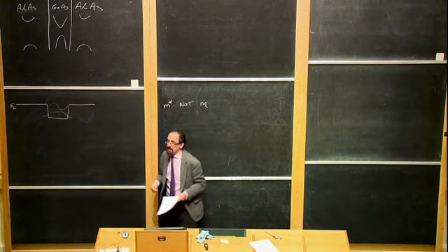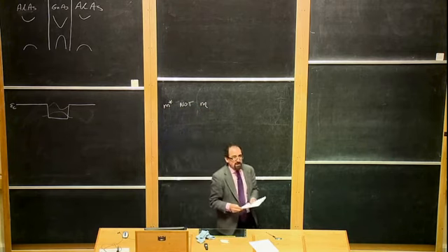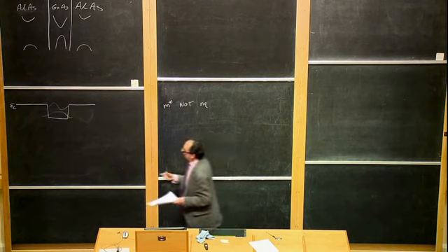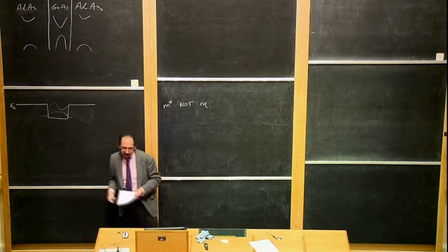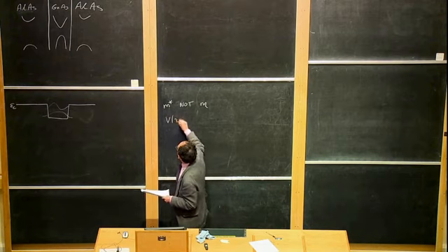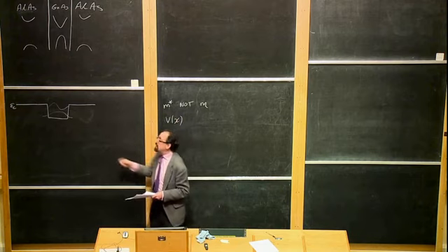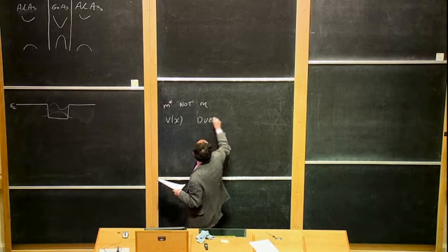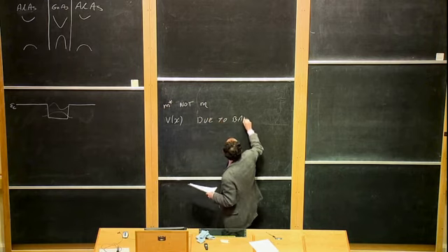The effective mass of the electron in the conduction band is the important thing that shows up in Schrodinger's equation, not the real mass of the electron. And the other thing that's different is that this V of x, this potential, is actually due to the band structure.